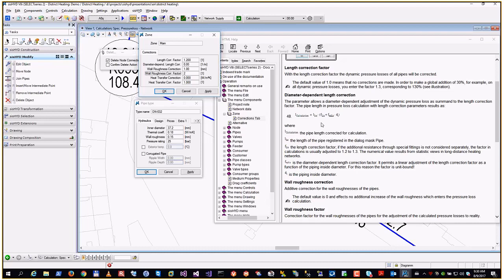I think you can do it for the main pipes in situations where there is almost constant load, and then you have reliable pressures and flows, and with the computation you know how to correct your flows.